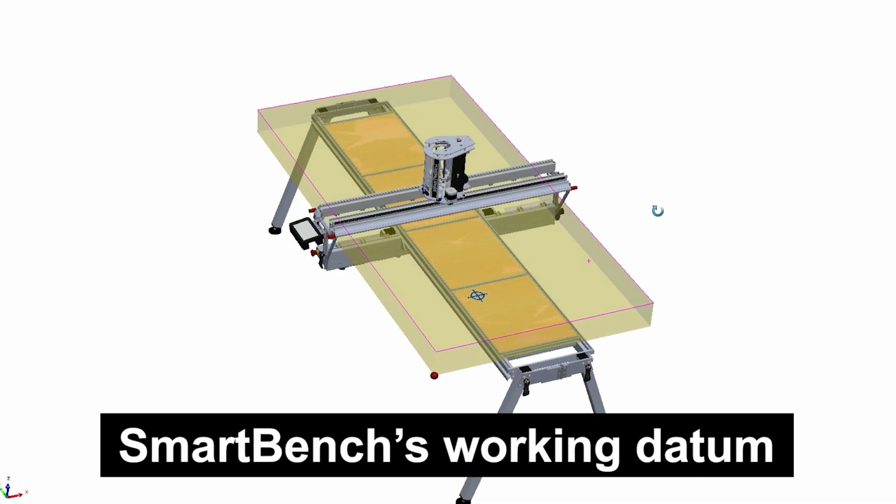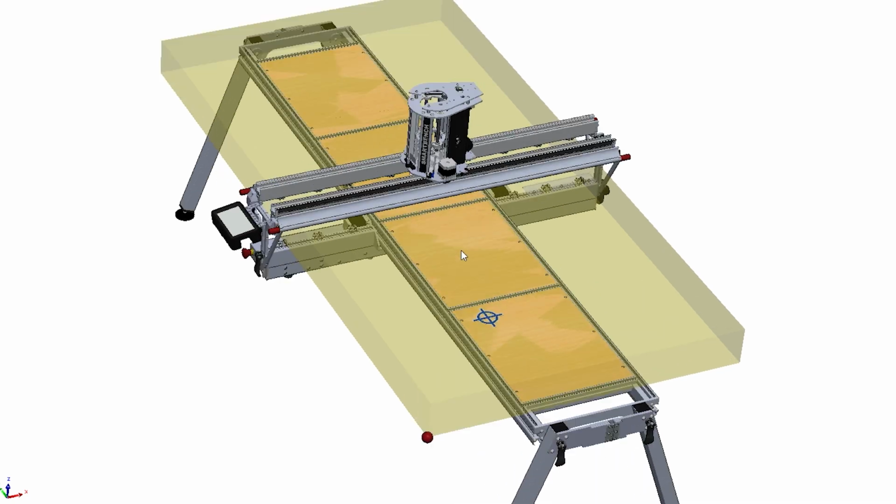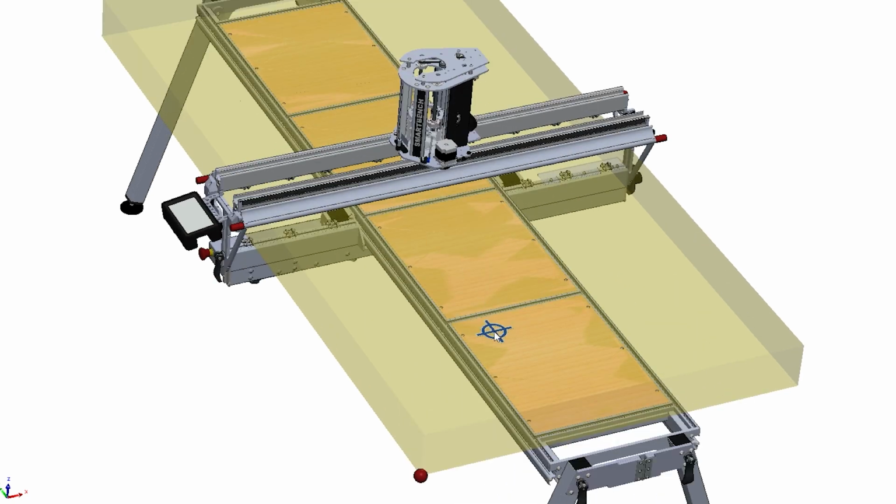Now let's have a look at SmartBench's working datum. Here the yellow box represents SmartBench's working volume or workspace. SmartBench can set its working datum anywhere within this workspace. SmartBench sets its working datum in 2 stages. Firstly in the XY plane and then in the Z axis.